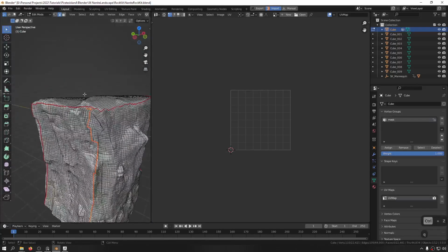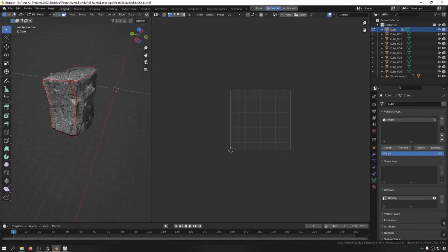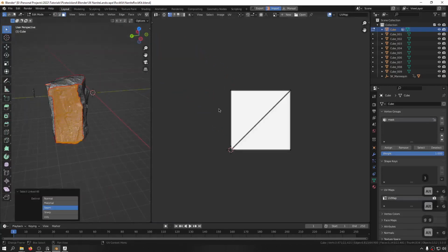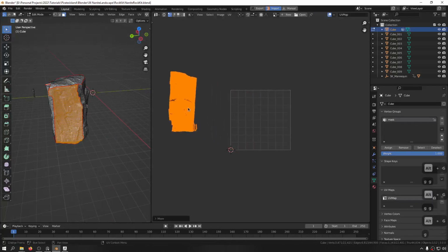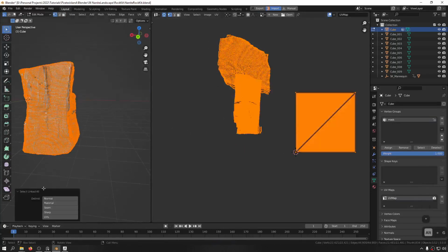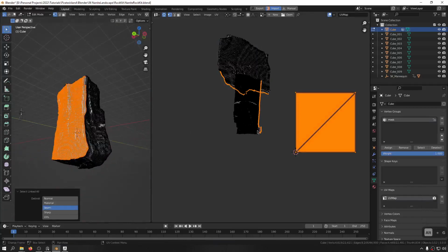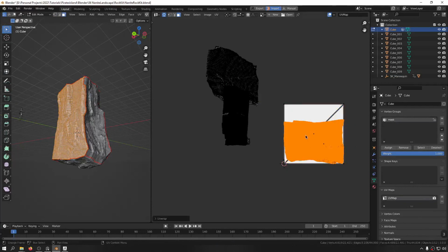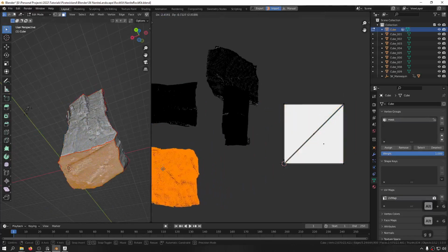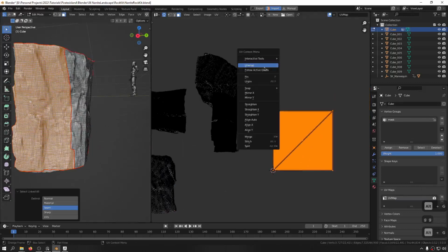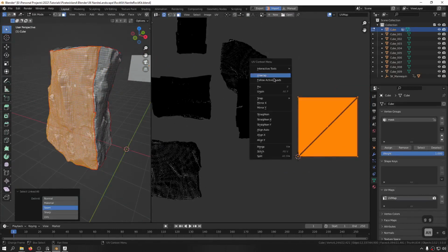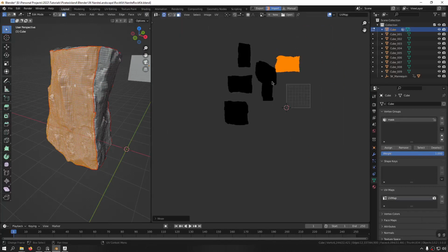So I believe the UV creation needs to be started on this. So let's go to polygon and I start to select this and unwrap. Okay, and select this one and unwrap. And of course you can hit tab to see the UV active mode and separate by seam. Okay, let's make this one a separate unwrap as well. This part unwrap, and this one unwrap as well. Looks like one more UV island remaining. Unwrap, okay, and now everything has been unwrapped perfectly.